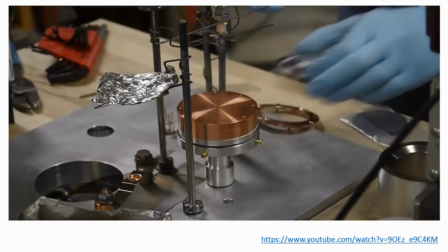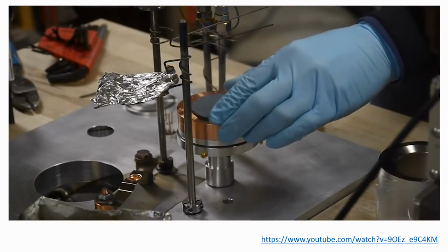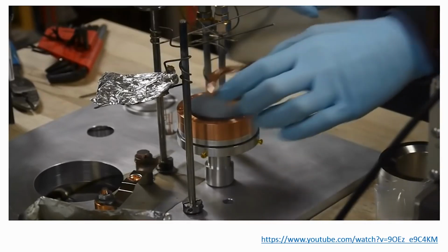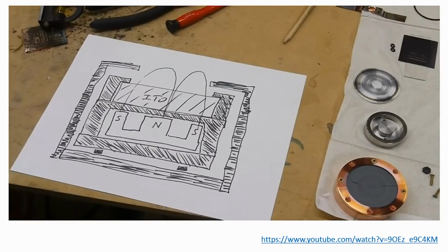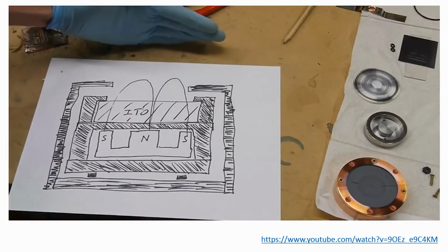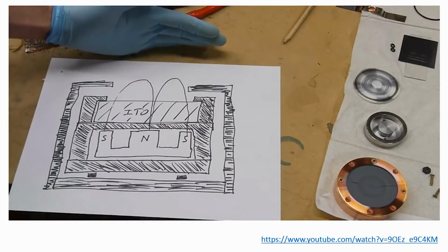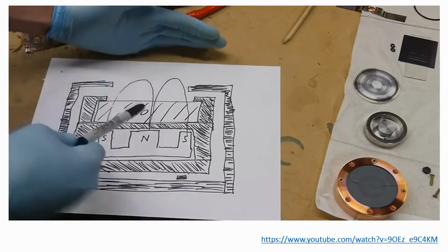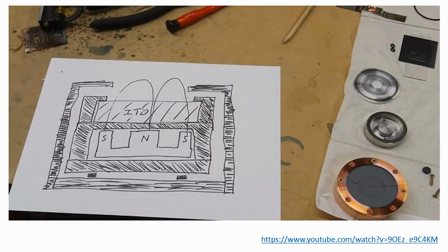Another problem is that if you have tons of gas molecules up here, when you eventually do sputter off a piece of the material, it's going to hit those gas molecules. And that may or may not be a good thing depending how your setup is configured. So if your surface to coat is kind of up here, you generally want these sputtered molecules to have a fairly clear path toward it. If there's so many gas molecules up here that a lot of the sputtered material interacts with the gas and kind of starts flowing, that may be a bad thing because they're going to escape and coat other things on the surface of your chamber.